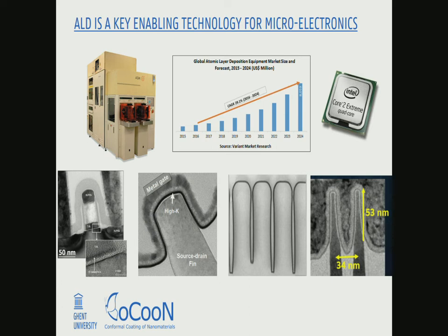So you have this annual growth rate of 30% that's being predicted, and that's also already being realized in recent years. It is mainly related to high-K applications for processors and for memory, and in recent years a lot of applications in this patterning. And as devices continue to shrink and to become more and more 3D, people are expecting more and more applications of ALD to emerge in the field of microelectronics.